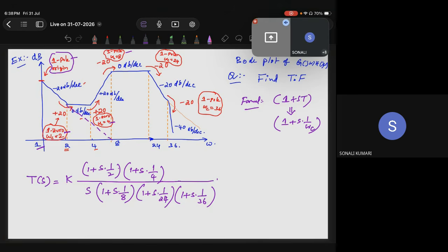Okay, so now what you do is you have this x-axis value as 1. The y-axis value you don't know. Let us call that y. And this line, as you see that slope line, is extended till 8. You can say the x-axis is 8, y-axis is 0. Here, these are not simple x and y axes. These are logarithmic scales. How do I write that? What is the slope of that line? The slope of that line is minus 20.